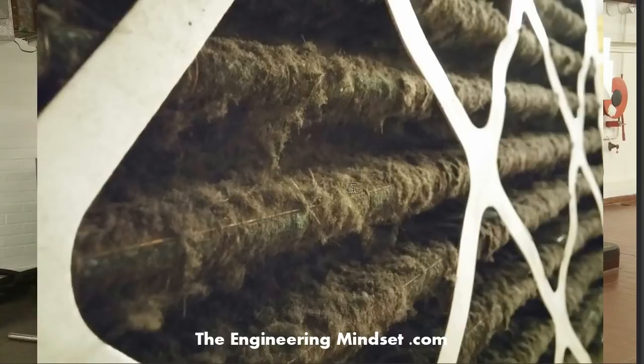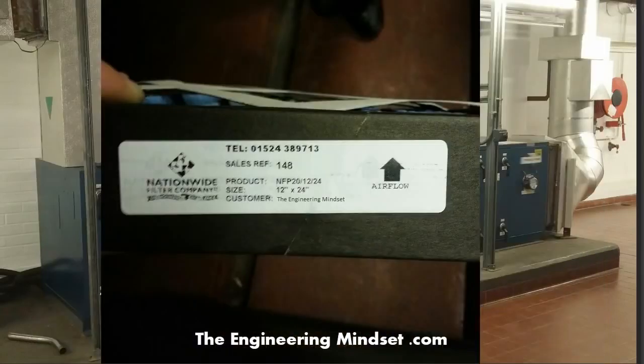So this is why it's important that you have filters on your airstreams, and that you clean these regularly, just to make sure that that is not entering your building, well, into your equipment, and also that the occupants inside are not breathing this in. You'll also find some information on the side of most of the panels, so you can see the size there. You've got the product description and the company who makes it, but you've got the size of the filter there. This one's in inches, who the customer is. I've just edited that quickly.